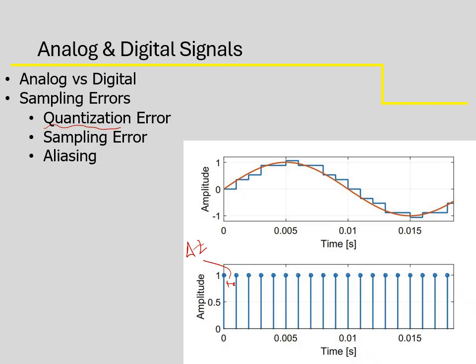And up here, the signal has gone up, the red line's gone up, and now we're taking the next sample. But you see that corner of that digital signal is a little bit higher than the true value. That's because the sampling system can only take measurements at certain spots. We see that exaggerated up here too. And we're seeing an issue here and an issue here where we're not quite getting the right values.